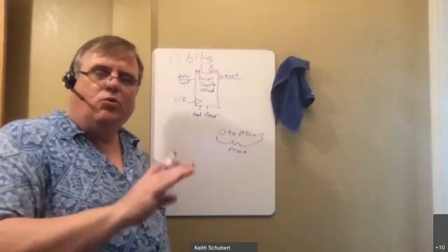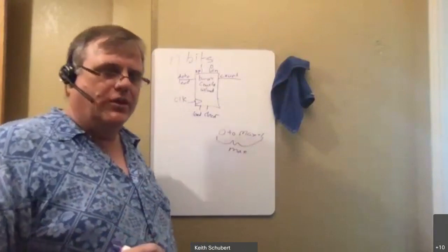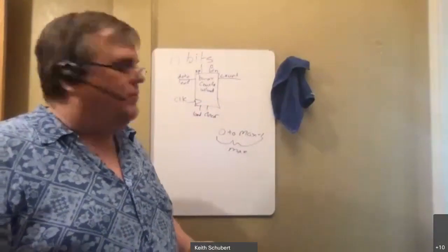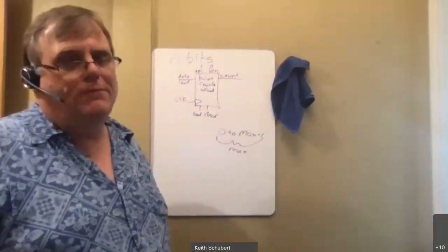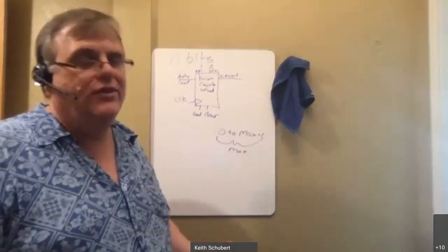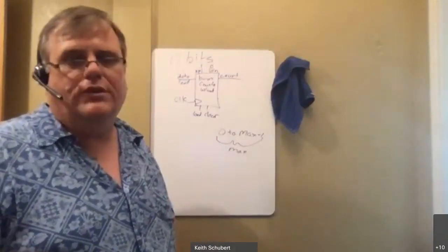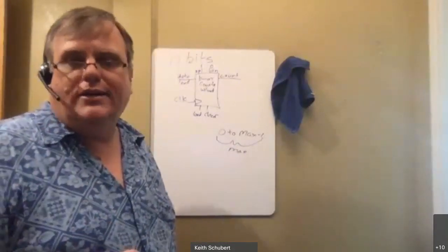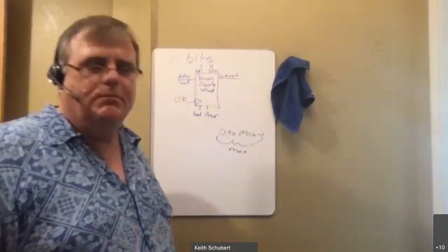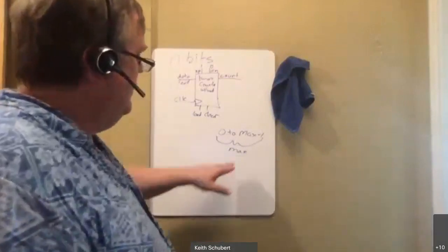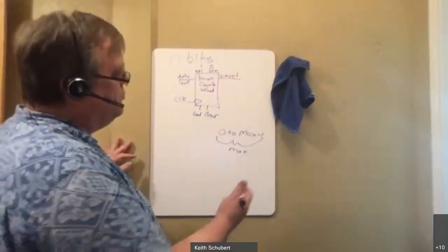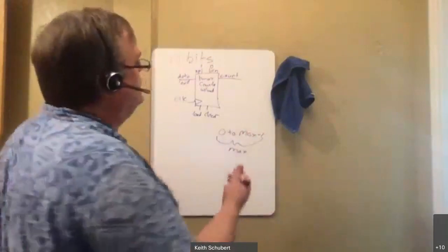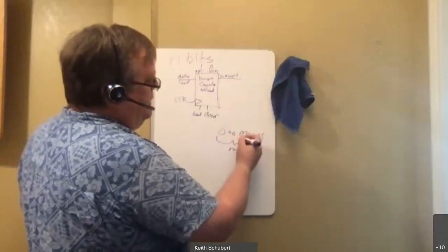Now, the reality is when you're doing this for the visual display part of it, it's not so precisely 1 million or whatever, right? You'll calculate a number, like you'll say, maybe I want 75 hertz or 50 hertz. That's what I want, right? And you'll calculate an exact number. If you're off 1 or 2 for a human display, your eye cannot count that small of a time unit. It cannot count that single 50 megahertz clock. You just cannot see millionths of a second. So it's not as precise here. For those cases, I would pick whatever number is an easy number right in that zone to make your life work nicely. But let me assume that it is precise.